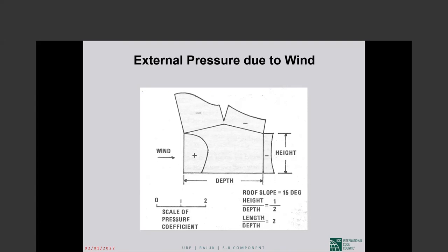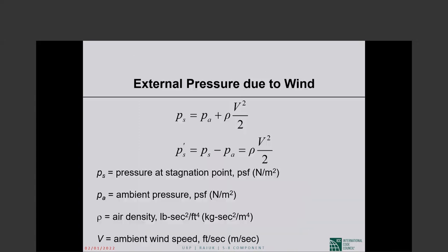That's because the anchor bolts are flimsy or non-existent. The bolts that anchored the building to the foundation. Now, in concrete construction, none of this can happen, obviously. You don't have a wood structure anchored to a foundation. But still, there are non-building structures, there are tanks, there are things that are attached by anchor bolts, and you have to be aware of this huge suction that wind imposes.